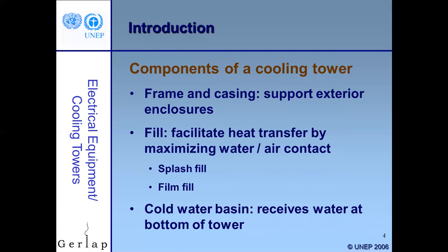These days fill is mostly plastic in different configurations, in order to break up the water either into small droplets or to cause it to create a film. There's splash type fill and film type fill that we'll talk a little bit about. It turns out that in most cases the film fill is actually a little more effective.